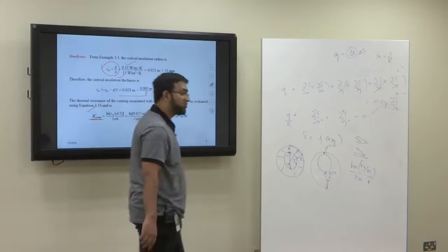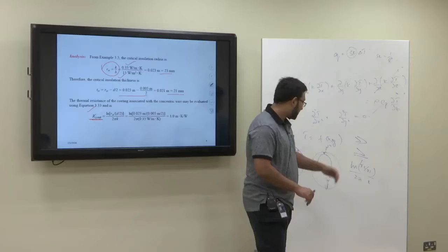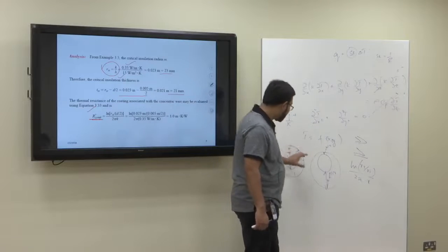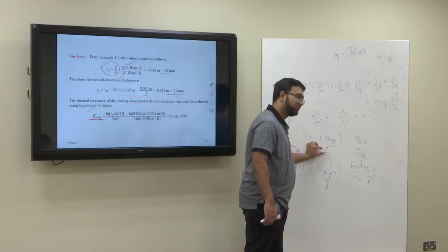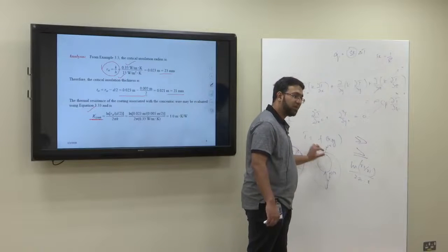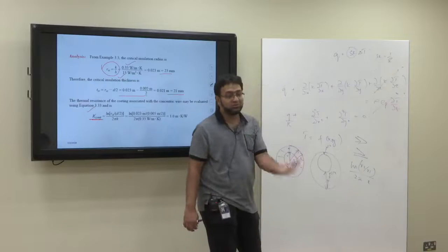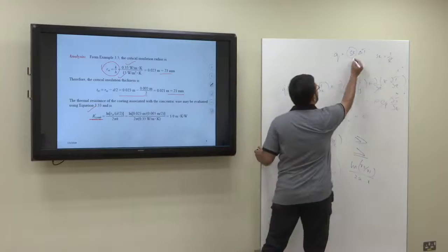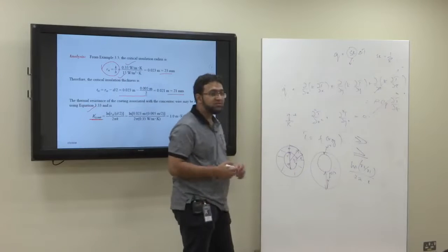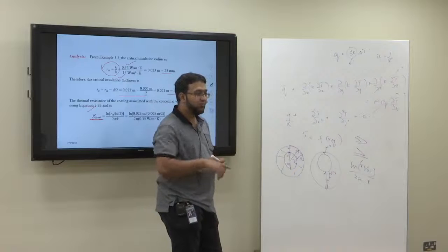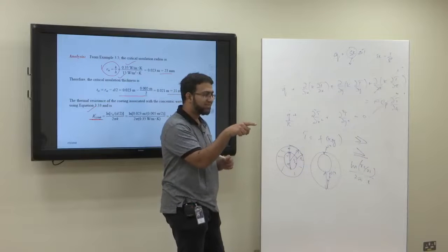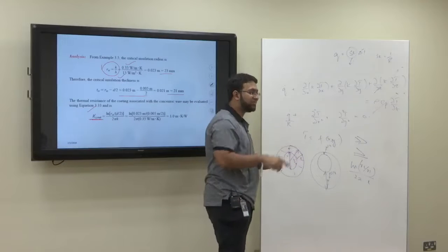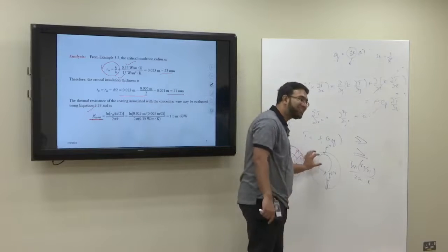So now we need to find the change in resistance. We know what should have been the original resistance. But in our case, the thickness here is changed because of the eccentricity. So now I need to know the new resistance, and the resistance is this Sk. From the table, I think it's case number 7, we can directly find out the resistance if you have a certain eccentricity.